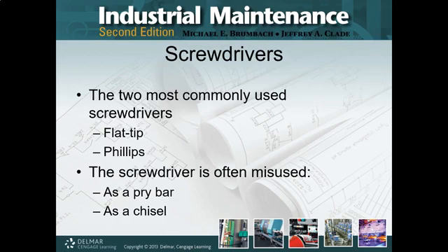Screwdrivers. The most common types are flat tip and Phillips. Flat tip is our regular everyday screwdriver, not the drink, the tool. And then we've got the Phillips, it's cross tip, whatever else you want to call it. But then we get all sorts of different screwdrivers out there. Now there's specialty screwdrivers for just doing the terminal screws on receptacles and light switches in residential and commercial buildings, or I should say commercial installations.